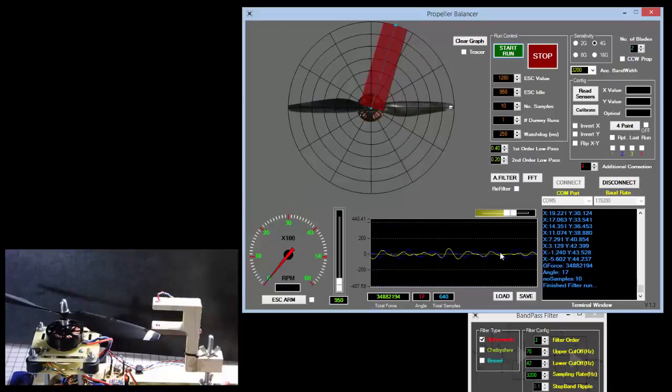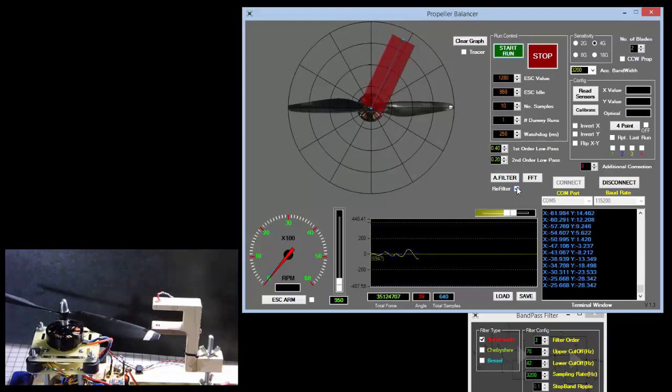You can try to bring these numbers down. Don't pay as much attention to the width of this because I have normalized it to about 16 million. So when this number begins to get below 16 million, you'll see this line get thinner and thinner, which basically means there's room for improvement, right? It shows us here that there's some sort of an unbalance in the hub, so you can add a few pieces of tape more to try and alleviate that, and we can keep refiltering, but we can also confirm